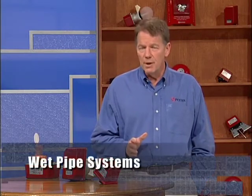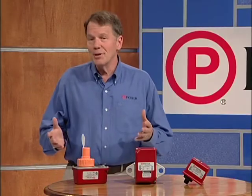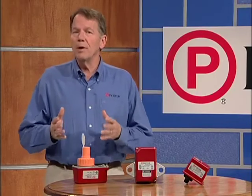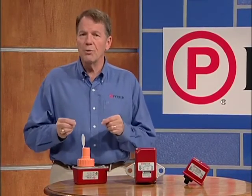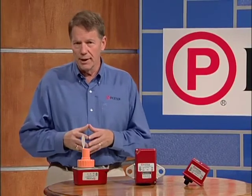Knowing what type of sprinkler system you're working with is the first step in assessing what monitoring equipment you and your customer will need. The most common types of sprinkler systems are wet pipe systems and dry pipe systems. As the name suggests, in a wet pipe system, water always remains in the pipes, and the system is connected directly to a water supply.